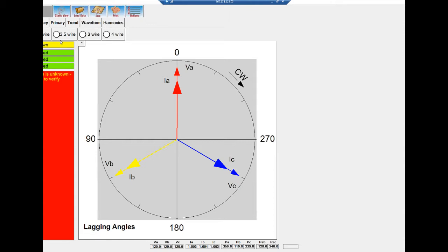As a precursor to talking about power quality, I want to talk about the setup I've got going here so you can understand what you're seeing. I am generating behind me a 120 volt three-phase service, 1 amp on the secondary and 20 amps on the primary. So I have 20 amps going through the primary of 3 CTs behind me, which is then feeding the 100 to 5 CTs and then generating 1 amp into the secondary of all 3 phases.